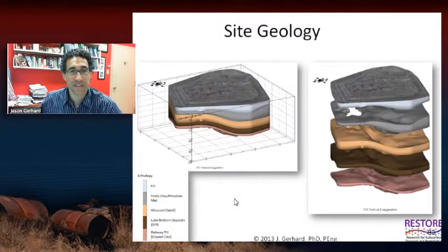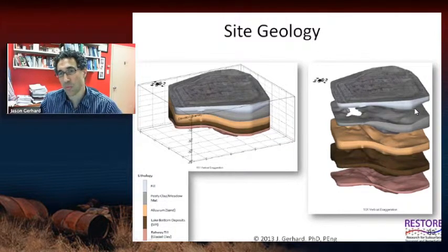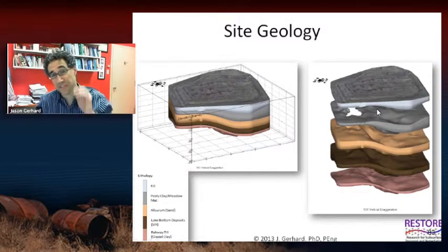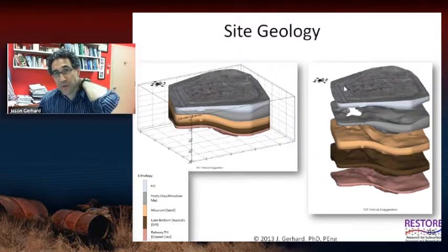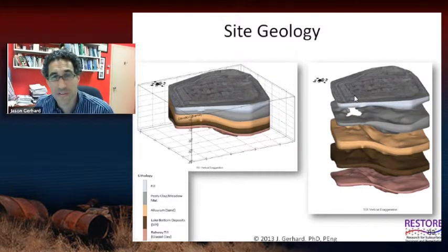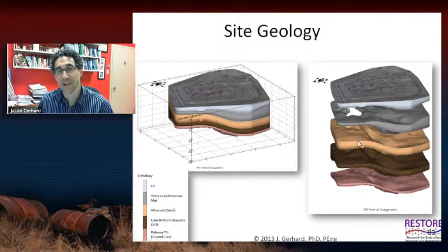So this is what the site looks like. Here's the site map I showed you earlier, and here's the industrial fill, which is about 1 to 3 meters deep on the site. And beneath that is this peaty clay called the meadow mat. It's a clay that's thin at one end of the site and much thicker across the rest of the site. And when we did some detailed site investigation, we found a window. You can see the window here, and that's another word for a hole, in the meadow mat. And that wasn't discovered previously. And this is exactly where the lagoons are. There's about 1, 2, maybe about 6 lagoons around the edge of the property here. And there was concern then that the contamination in the fill layer, the lagoon, the coal tar, might have percolated down into this underlying sand unit.